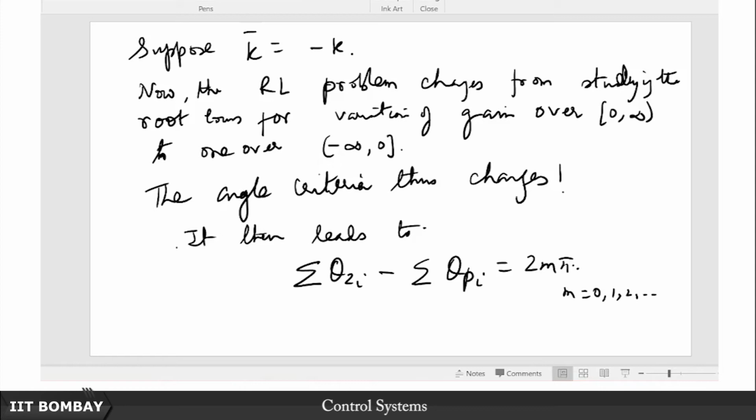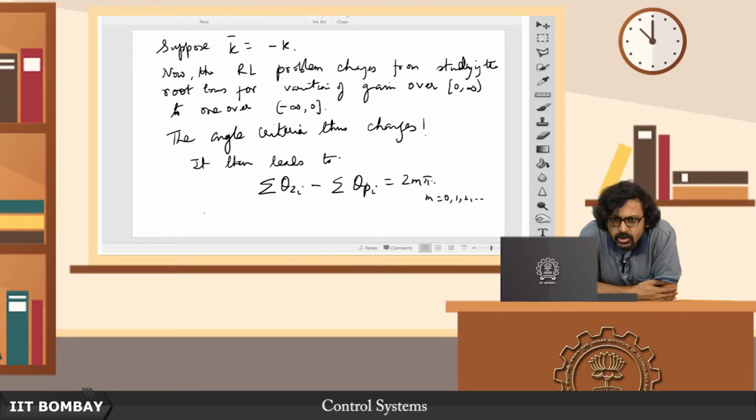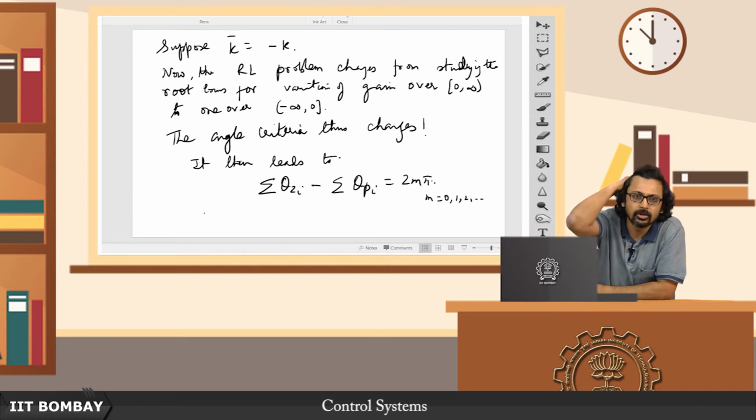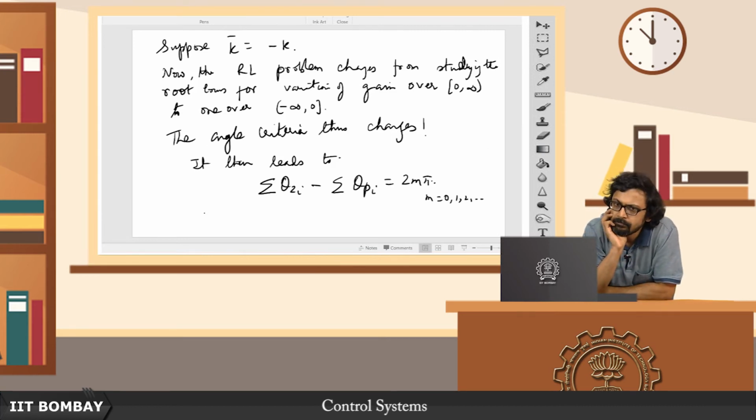Along which directions? Well, of course that will change because of this angle criteria. So the direction of asymptotes changes. Number of asymptotes does not change. Location of intersection of the asymptotes does not change because the angle criteria has nothing to do with that derivation, if you recall.